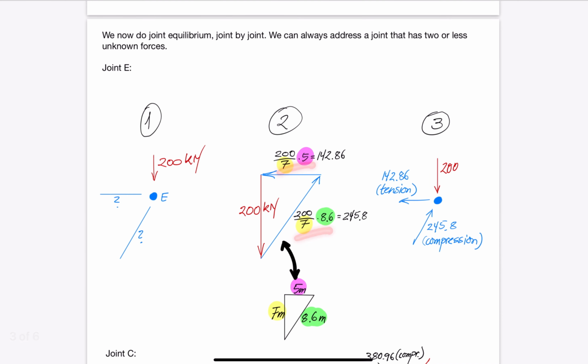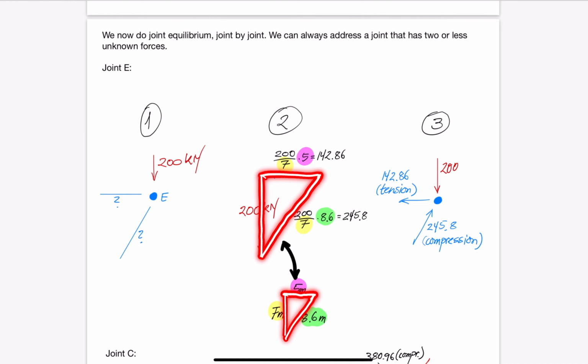Notice the triangle shown below, which is taken from the truss, with lengths in meters, compared with the triangle that forms a closed force polygon. One message to take away from this drawing is that we simply do triangle equalities for the sake of geometry. We do not need to have the sides of the geometric triangle be actual members of the truss. We just want to have a geometrical shape that compares with the shape of the force polygon.